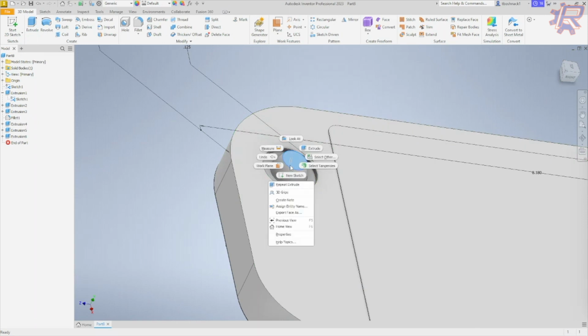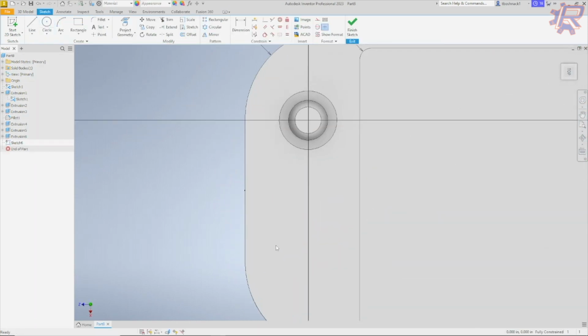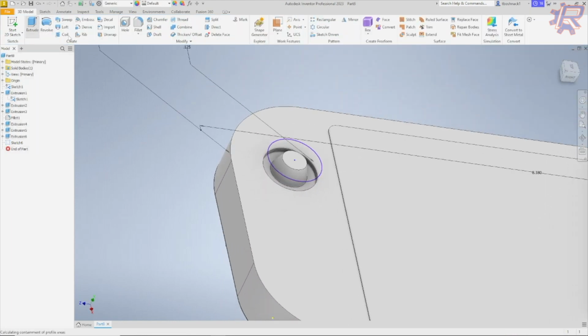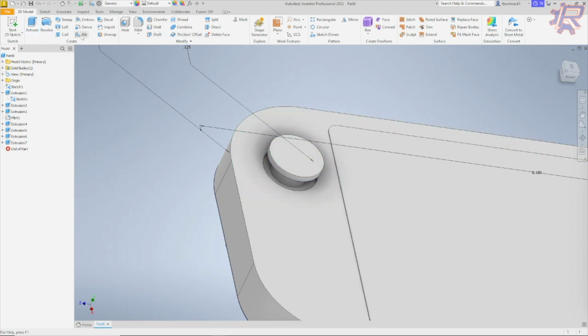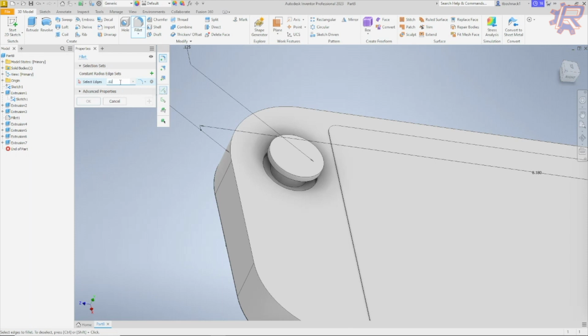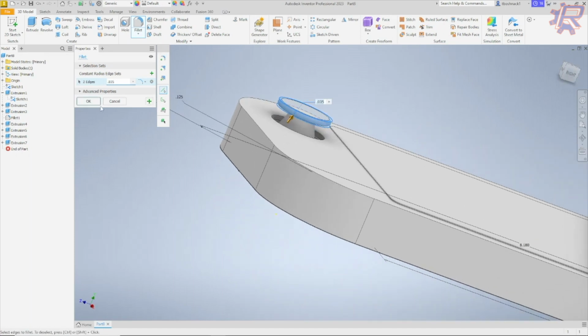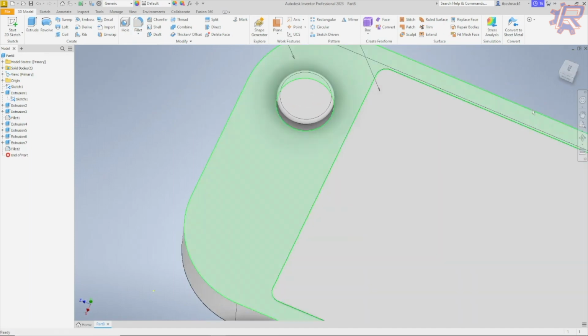Now on top of this, again, we're going to make another sketch. And this is going to be the same diameter as the original circle. It's just going to lock in like that. Finish sketch. And we can extrude to 0.07. And then again, to make it rounded, we could use a 3D Fillet Tool. And let's use 3D Fillet Tool 0.035. And then you have that nice rounded Joy-Con.